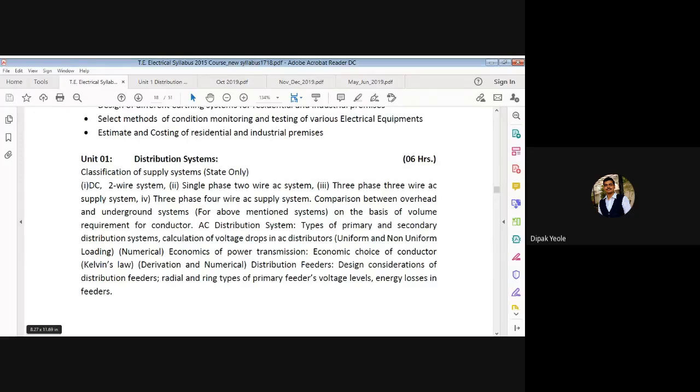You know that whenever there is a system, obviously there are advantages and disadvantages. The advantage of thermography analysis is that it is a non-contact operation. That is an important advantage. Non-contact. Yes. Rapid scanning is available, so that is the second advantage.